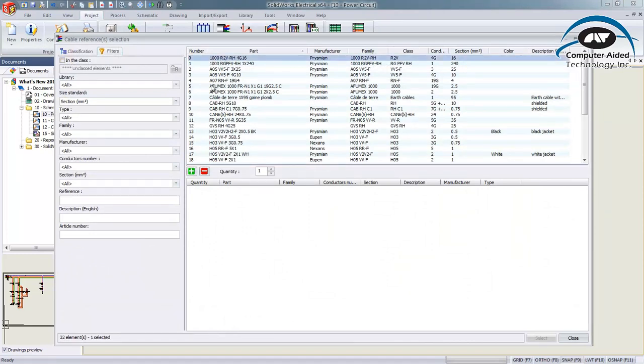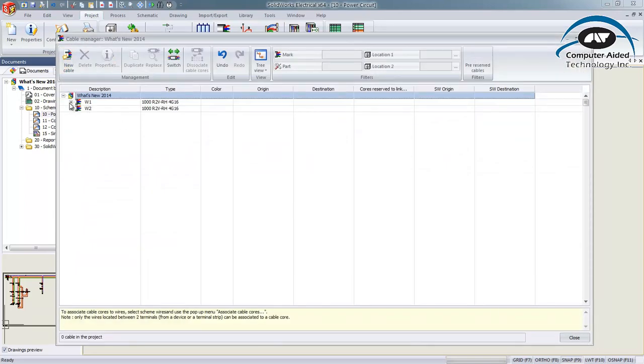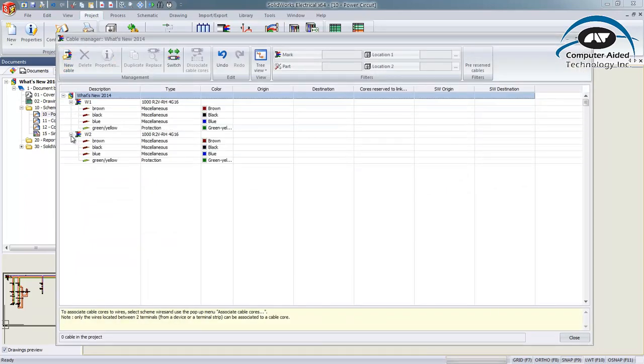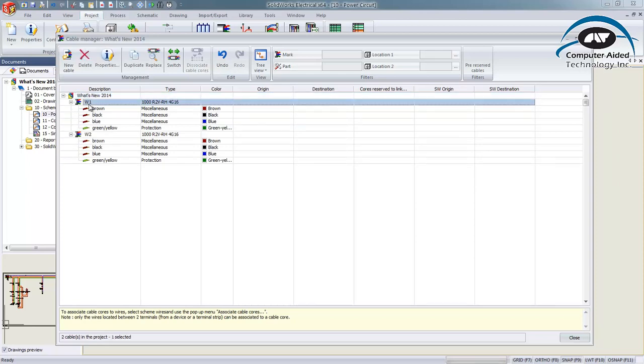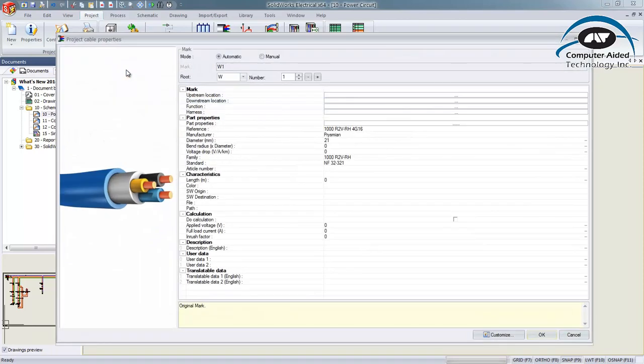After choosing some cables from the vast library of cables available in SolidWorks Electrical Schematics, we can manually modify some properties. The length, for example, is automatically calculated when wiring your system in SolidWorks, but can be overwritten. In addition, SolidWorks Electrical 2014 also lets you define the bend radius and the voltage drop.